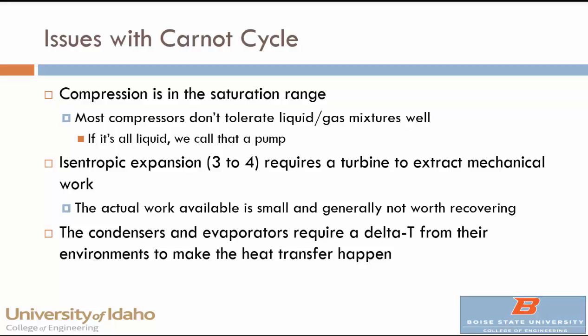Another issue with the Carnot cycle is that the isentropic expansion from 3 to 4 requires some device that does work and some place to put the work. And that's a little awkward. For one reason, there's not a lot of energy involved. And for another reason, it's just another device that has to be designed, built, and maintained. So it's not a lot of work to recover, and it costs a lot of engineering and manufacturing, so we're not likely to do that either.